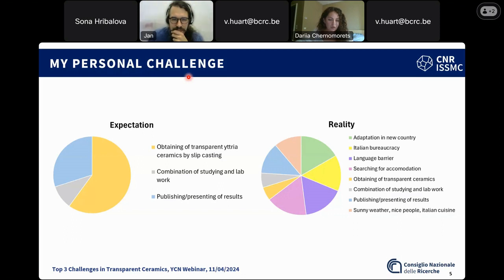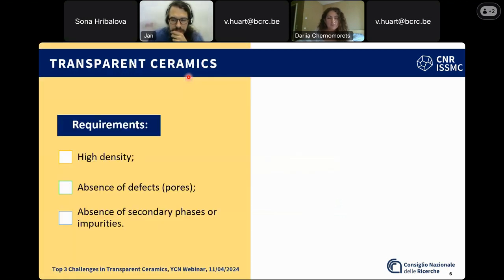But achievement of the required rheology of suspensions leads to a dense green body and absence of defects such as porosity. So highly transparent ceramics can be obtained. And that is the last challenge in my presentation, but not the last in the real work. After selection of powders and shaping method, a new question actually arises: how to reach full density.